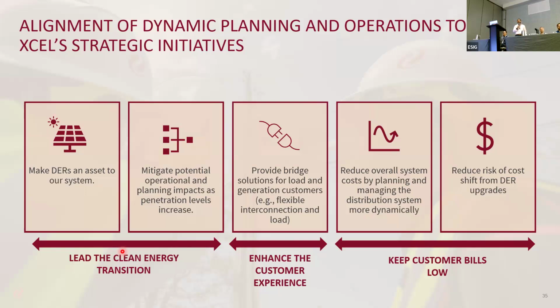If you look at states like California with net metering 1.0 and how that's evolved, there gets to be a point where direct customer benefits don't really provide a benefit to the overall system, the other customers that are overall users of the grid and how that grid is paid for. So we're trying to find ways that we can position DERs actually as an asset to the system. Some of that comes with things like locational value and being able to do things like flexible interconnection.